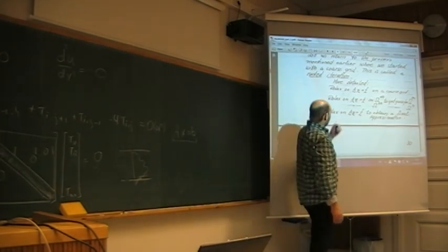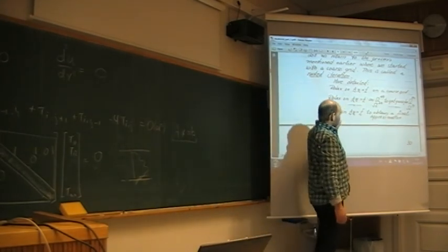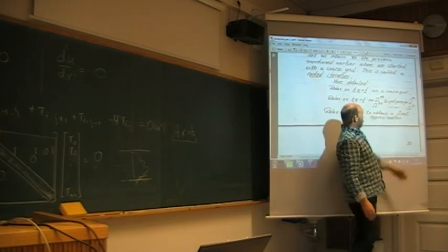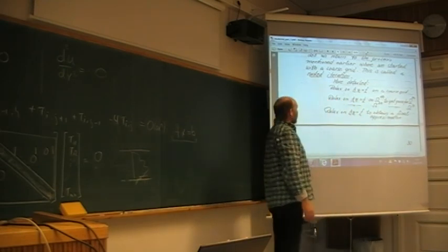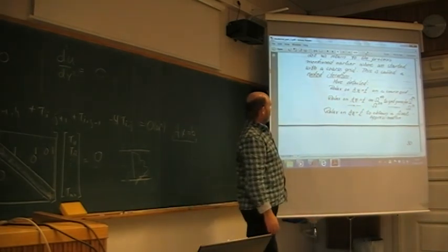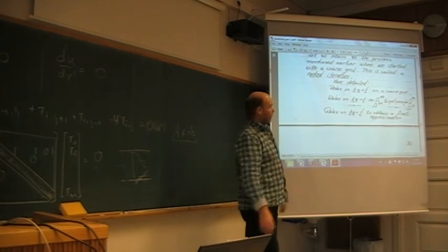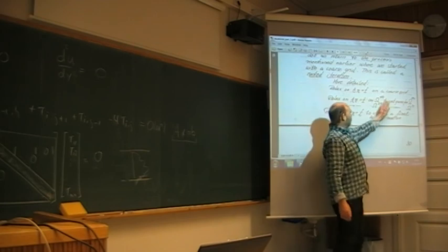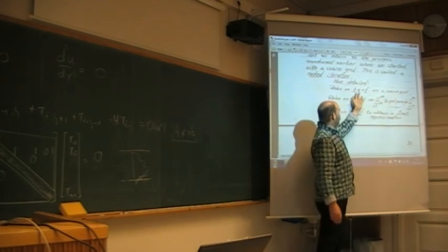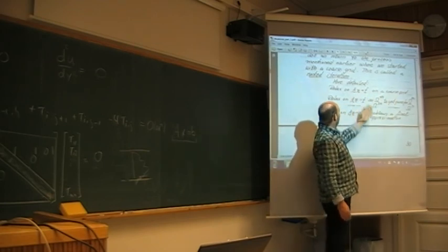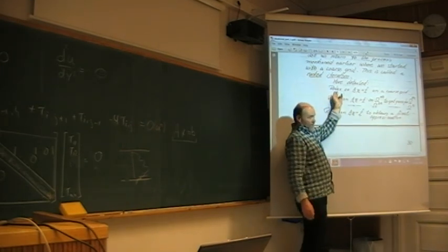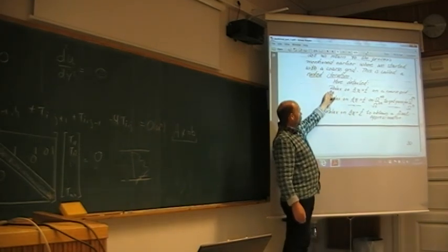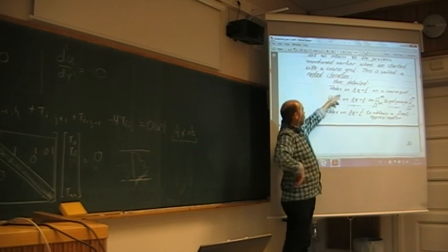Actually here they start on a coarse mesh, because you haven't even gotten an initial field. So you start where it is very cheap. Start on a very coarse mesh and see if you can find a solution there. When it says relax, that means one iteration or maybe several.